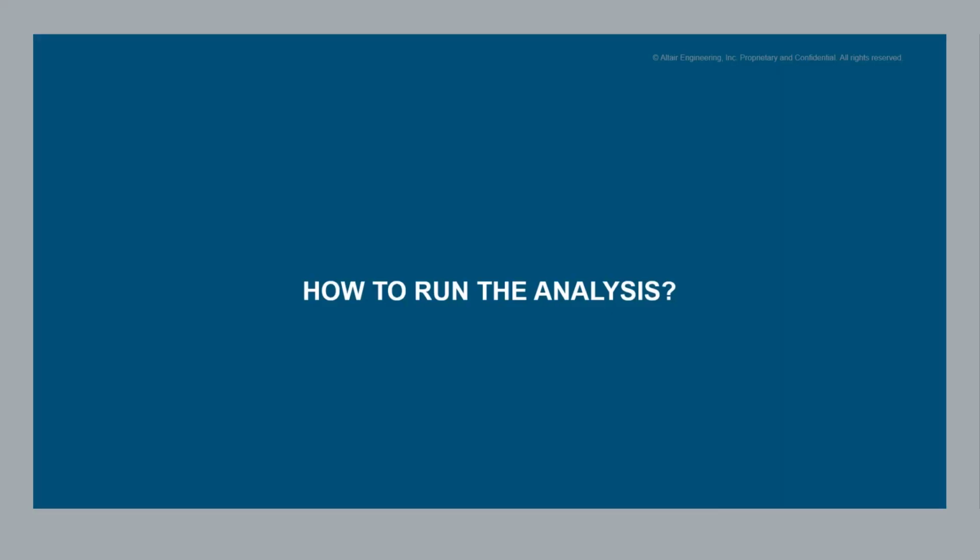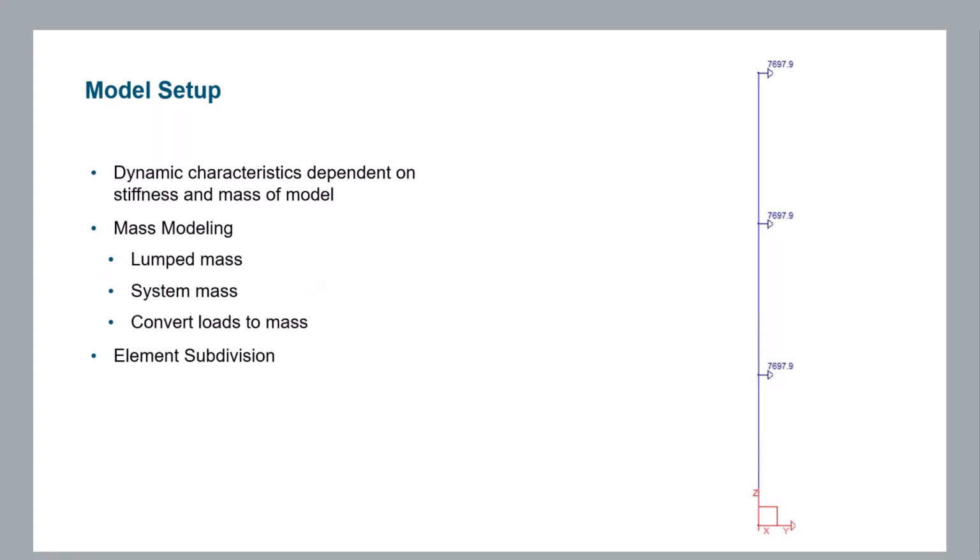I'm just briefly going to touch on how we can run a vibration analysis. Andreas is actually going to be doing a demonstration on this as well, so he'll be going into a little bit more detail than myself. But there are a few points to think about when we set up the model. First of all, the dynamic characteristics that I mentioned earlier, the natural frequencies, the mode shapes, and so on, are very dependent on the stiffness and the mass of our model. So it's good to put some thought into how those are represented.